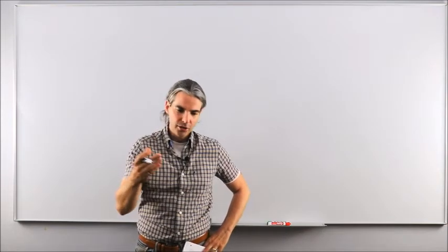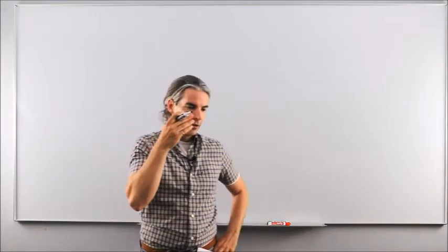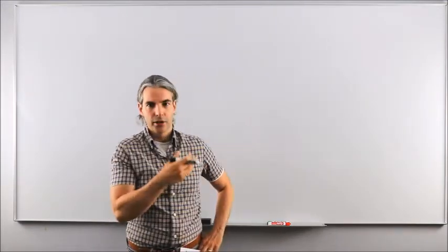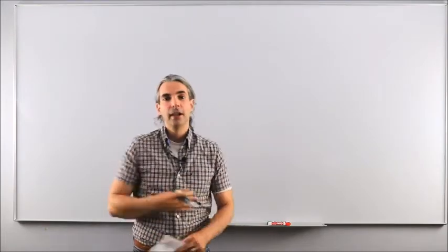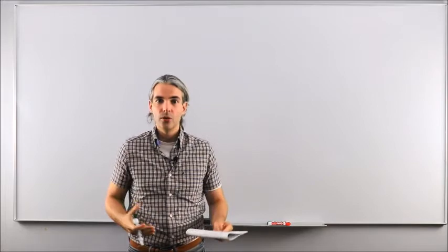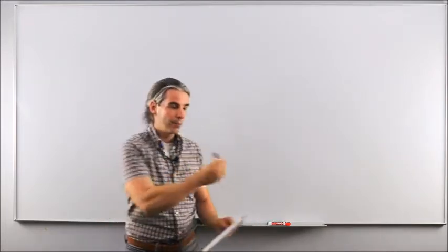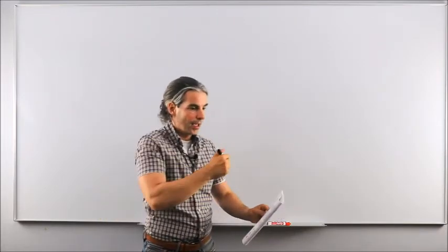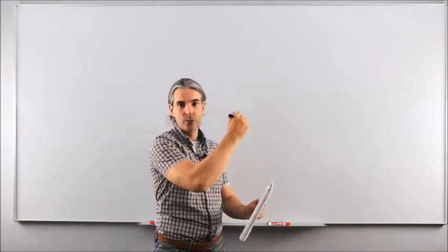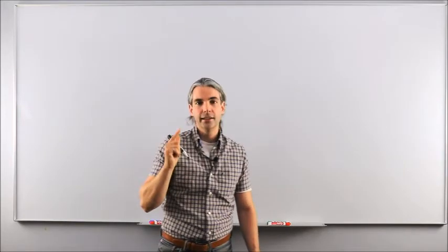So the idea here is to come back and say, okay, not a problem. I'm just going to throw another controller in front of everything, or a compensator that will add poles and or zeros to the system. And by adding those additional poles and or zeros, I'm going to modify the existing root locus and bend the branches to one side or onto the other side, and modify the location of the closed loop pole along the new branches. Okay? And that is the idea here.